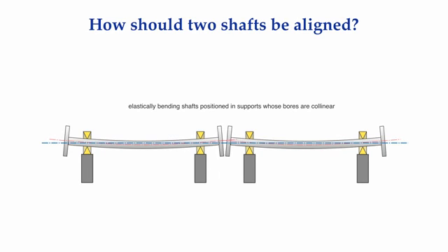If we intentionally align the bearings so they are collinear, then it becomes obvious that there is a misalignment condition between the center lines of rotation of the shafts. Again, be cognizant of the fact that the shafts shown here naturally want to rotate on their curved center line of rotation. This doesn't look right, so we need to probably raise the outboard bearings a little bit, don't you think?